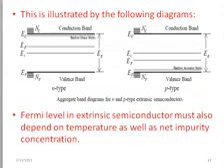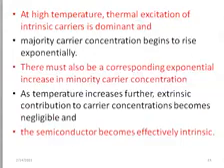And also the Fermi energy concentration for the intrinsic case, either p-type or n-type, depends on the temperature, because whenever temperature increases, there is increase in the breakage of bonds, and that will increase the majority carriers as well as the minority carriers. Now at high temperature, when the temperature is very high, you come to a point where the thermal excitation, that is breakage of the bonds due to increase in temperature, is now dominant compared to the extrinsic impurities we introduced.